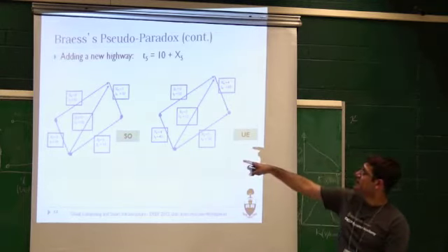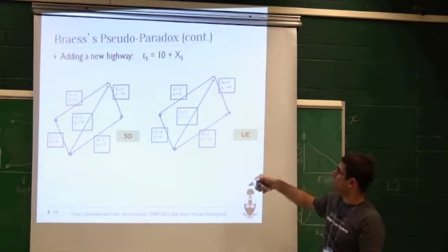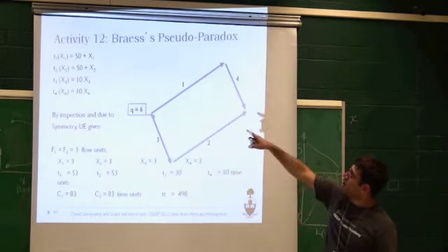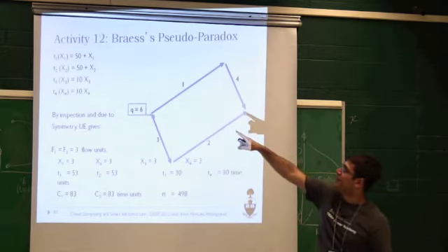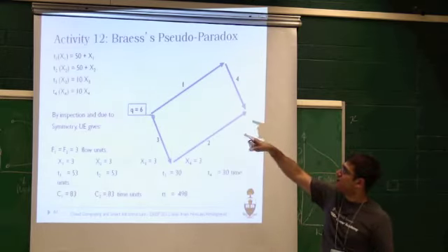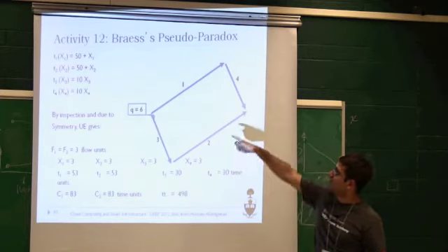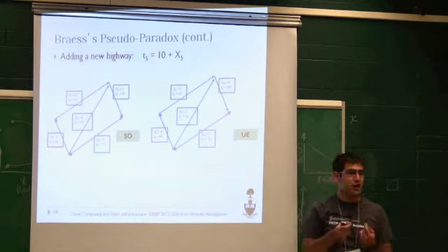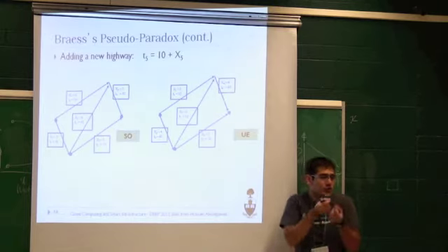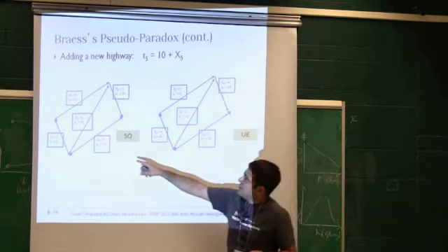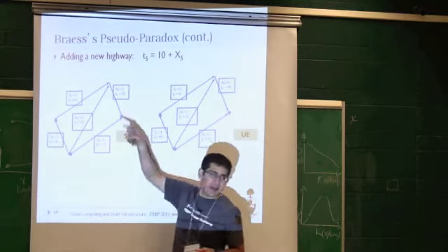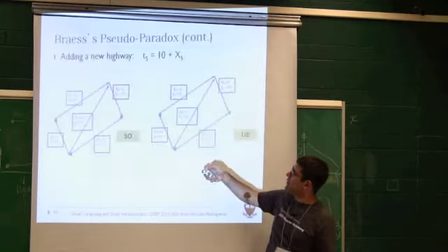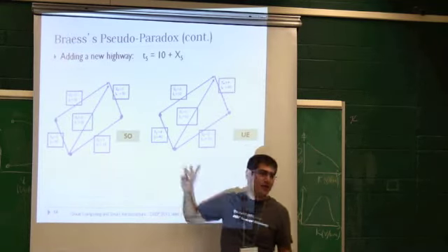Because this is the result of system optimal, this is the result of user equilibrium. The t is based on what x you end up getting. So these are the formulas. If x is 3, you end up getting 53. If x is 2, you end up getting 20, for example, on the third one, right? The solution of how much you're using over that link is here. So 3, 3, 3, 3. This was what we had before, right? That's why it's the same values as before.